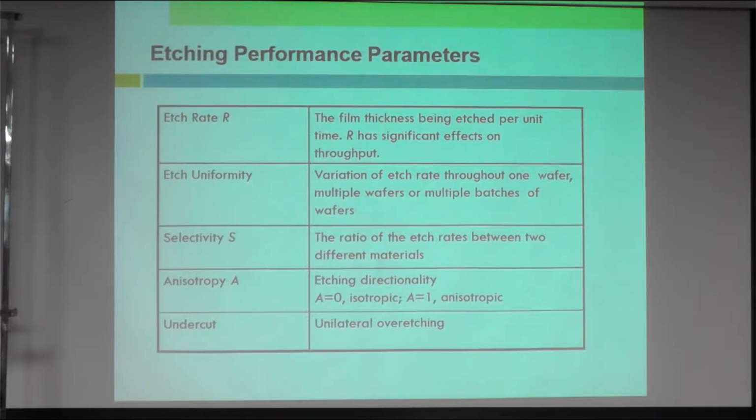As mentioned, different materials have different etching rates, but you have to cater the process time as well, because with the etching rate, you know that a certain material will be etched faster in comparison with other materials. But if you use a mask, for example, the mask has to withstand a certain time in order for you to etch the different thickness to be removed. Because we know that the mask normally is not as thick as the material that you are going to remove, in the case of patterning silicon.